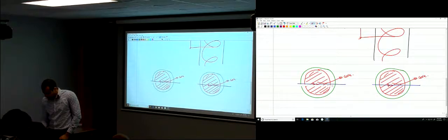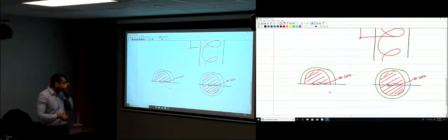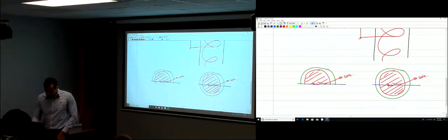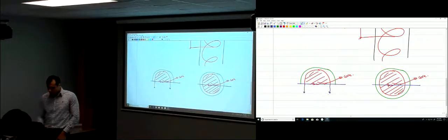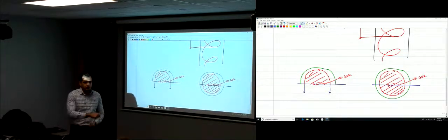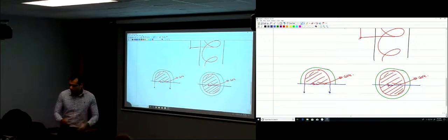Just 1/2 of that, applying an axial force, a longitudinal force on that column. There will be hoop stresses in the spiral. We discussed this last time, I'm just redoing that again in a slow way. There will be a tensile force in these hoops, tensile hoop stresses, and that will be confining the core of the concrete.